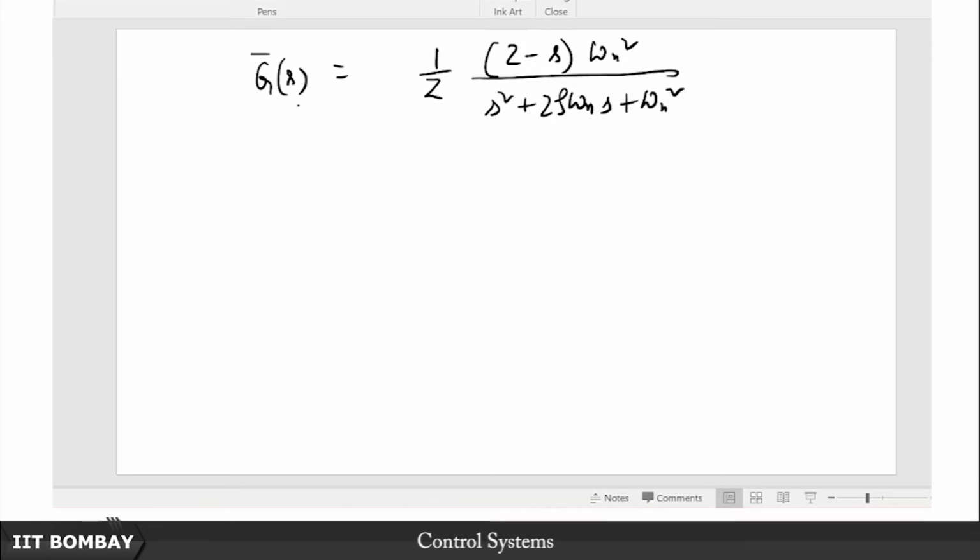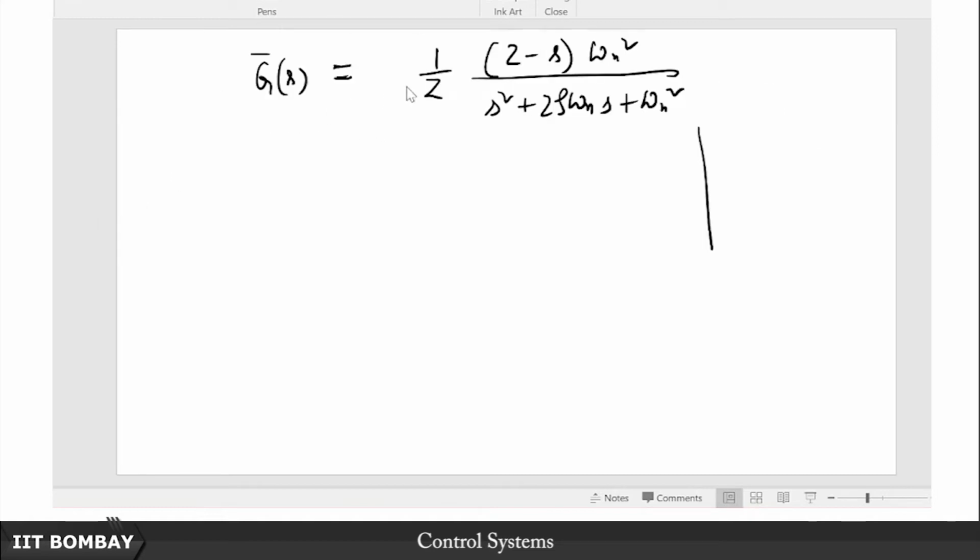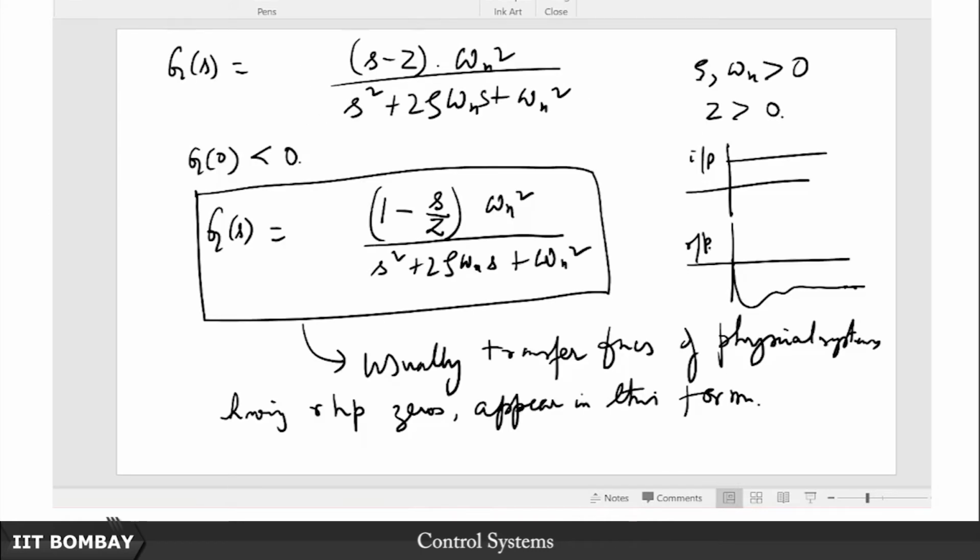So then, based on our discussion now, if we want to find out the root locus of this system G bar, which is actually what the physical system is, actually it is G, I'm just adjusting this. If I remove this z, then you can call it G bar, because G and G bar, the way I have defined them here, are just scaled versions of one another, so their root loci will not change, except that the closed loop gain for one and the other will be scaled by this factor of 1 by z.